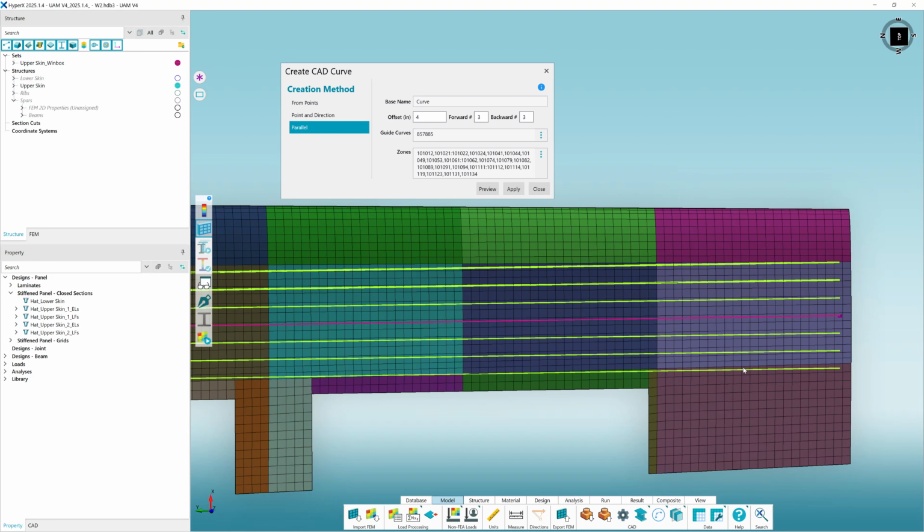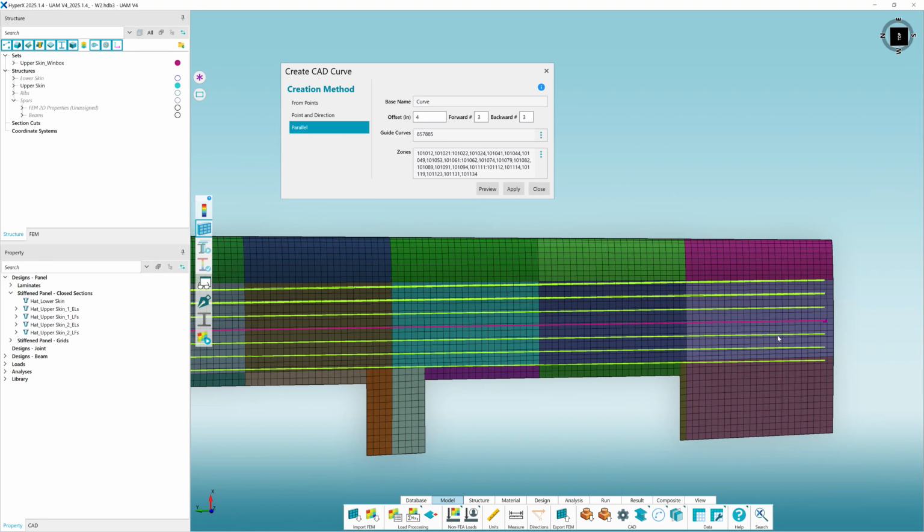They start to cross over the spar locations, which for some types of structures, like maybe a commercial aircraft type of wing, you would just terminate the stiffeners somewhere further back and maintain the parallel spacing. But for other types of structures, such as the one we're looking at here, you would probably want to taper your stiffener spacing so that you can keep all of your stiffeners continuous.